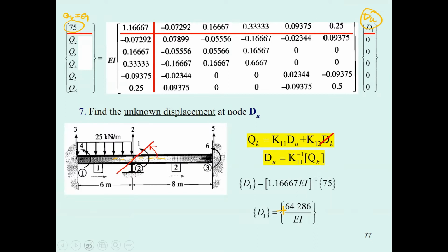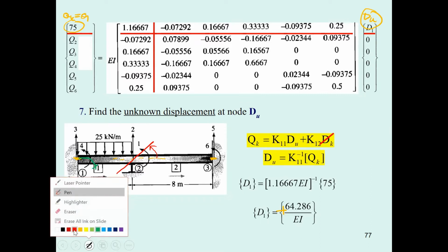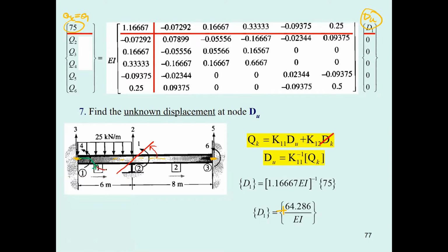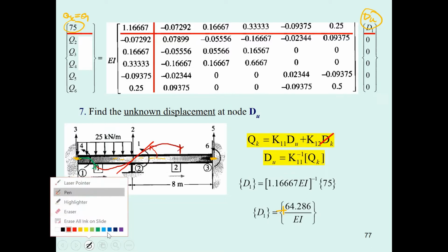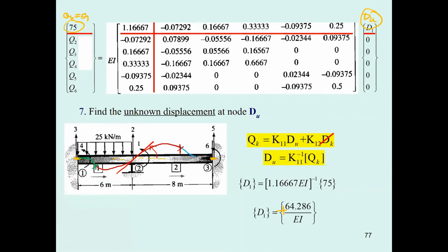And then if you are using your own knowledge about drawing the elastic curve, you can see this one is supposed to go downward due to this force, and then this portion must be reversed to have the tangential line over here, and then over here it must reverse back, something like this, in order to go to this fixed support.